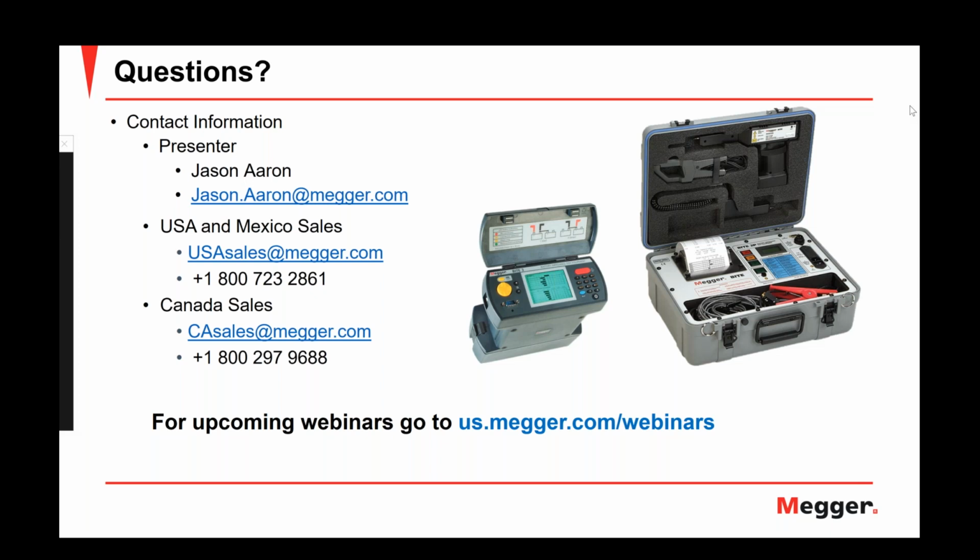It's a relative result that you get, and you have to trend this value, preferably, to be able to make any decision. You compare to a baseline, you compare to previous readings. In that sense, where the test has been applied the most, and where there are a lot of results, is for lead acid batteries. For other batteries it might be applicable, but you will need to find out how to analyze the results, how to make sense out of the values that you are getting.